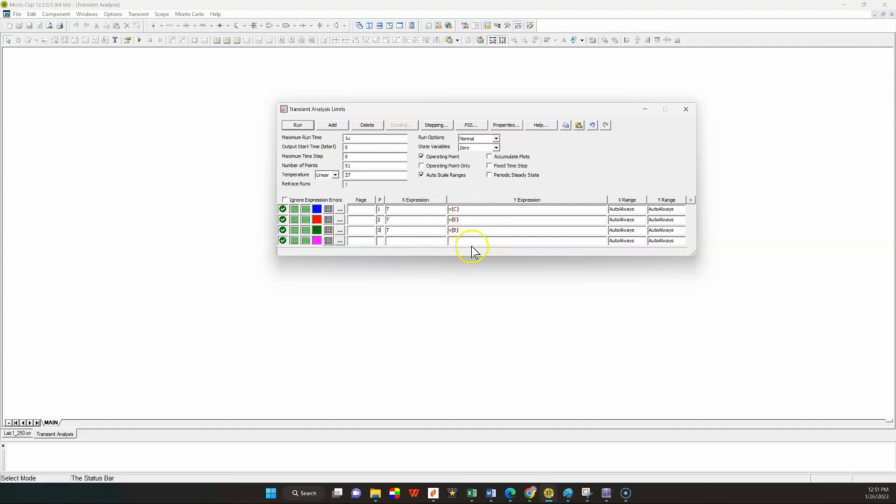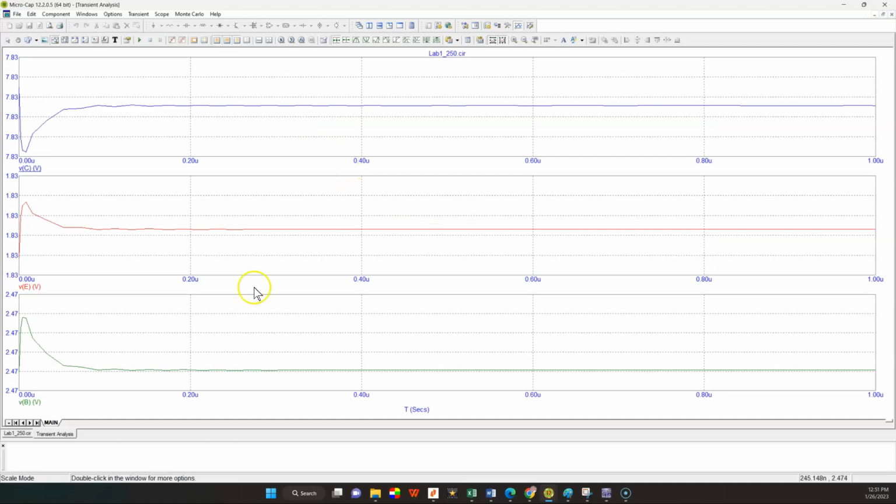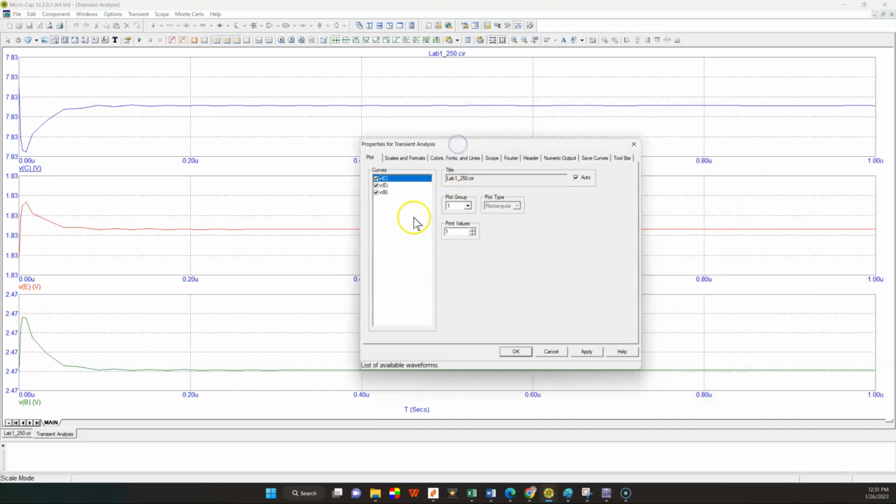All right. So what's next? You go and say run. Here you go. Then you see the result here happening, the values. Well, you don't have to pay attention now to what the graph looks like, but I'm going to show you if you want to change the range of Y or X axis. You just go there and double click with the left mouse, and then you will get the dialog box that will tell you which one you want to change.